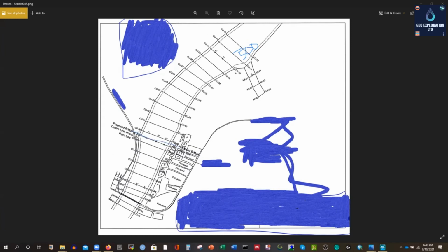This is the bridge center, and that is the center line, okay? And here upstream cross sections 1, 2, 3, 4. If you go upstream, your cross section number is increasing, and CU means cross section upstream. And if you go downstream, then we have D, right? CDS means cross section downstream 1, 2, 3. So the number is increasing as you go in the downstream direction.